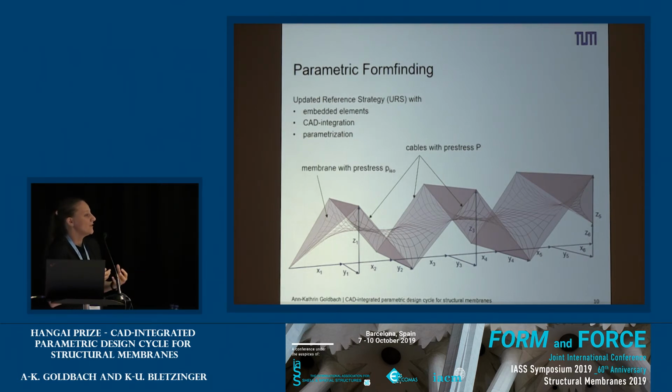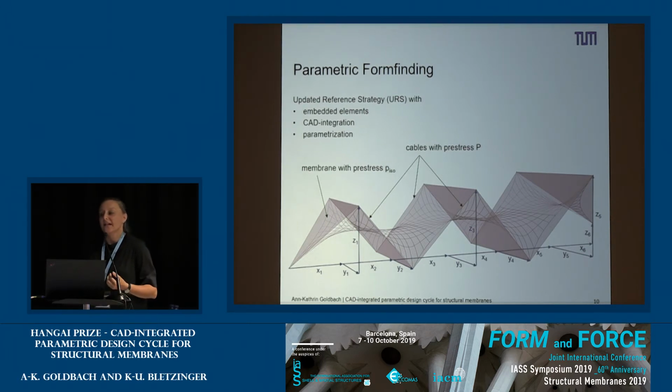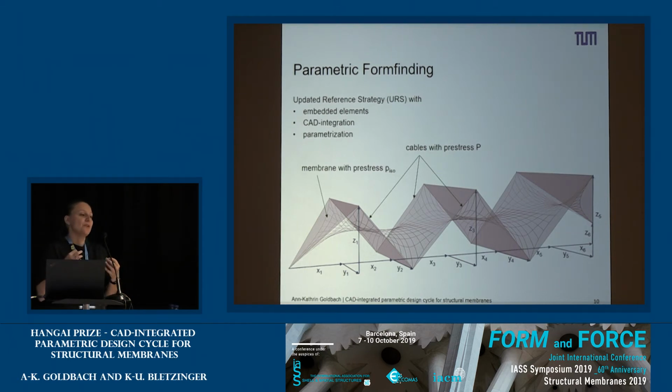And from a discretization point of view, again, this flexibility is possible because we use the isogeometric approach. So it doesn't matter how wide or how high I will make the structure, the discretization comes from the NURBS description, from the NURBS control points, and is therefore independent of the parameters I choose. So now here you already see the form-found structure.